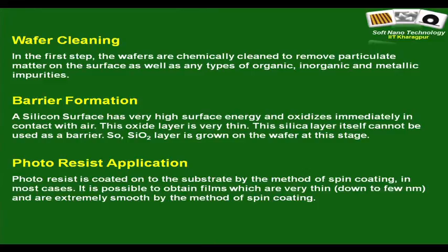In fact, in semiconductor processing or semiconductor industry, cleaning is an extremely important step, because, and I mean, nobody in fact knows what exactly is done, but it is believed that there are a whole lot of steps associated with different solvents. It is cleaned to remove all possible types of contaminants. So, once you have a cleaned wafer, you need to of course first dry it up, and then you start depositing the barrier layer or the silicon oxide layer, which is again a very simple step.